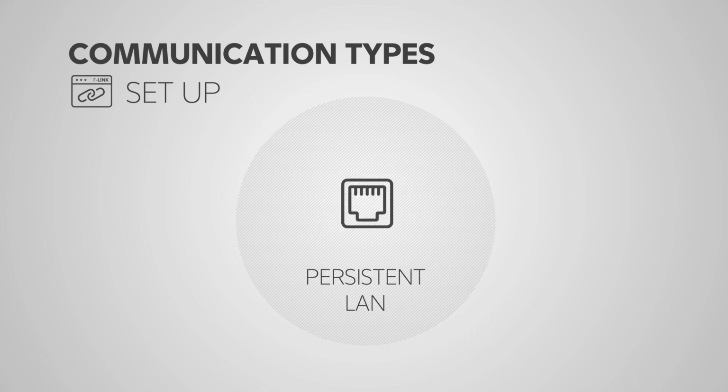The persistent LAN communication setting enables persistent communication to the cloud every 15 seconds as mentioned before. This setting uses data communication via LAN or GPRS. However, it doesn't send any big data such as temperatures, signal strengths, etc. The advantage is faster communication in the initiation of remote access by F-Link, as no initialization ring from the Jablotron CLOUD is needed.